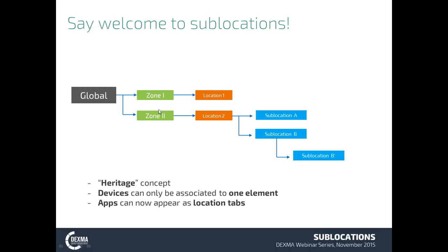Okay, that's so cool when talking about supplies, right? So for instance, in case you have many locations, but you don't really care about going to the cent of euro or the cent of dollar in every single bill, what you can do is create a general supply using an average price per kilowatt hour associated to a region or a zone of the project, and then all the children will get that information from it, and you save a lot of time.